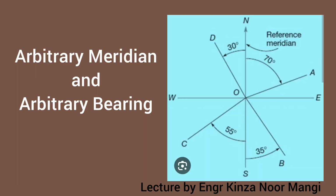Then comes the arbitrary meridian. Sometimes for small areas a convenient direction is assumed for a meridian, and such a reference line is known as the arbitrary meridian. The starting line of the survey is taken as the arbitrary meridian. The angle between the arbitrary meridian and a given line is known as the arbitrary bearing of the line.